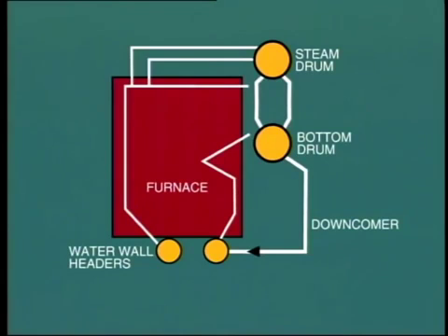Means must be provided for draining the boiler of water in the case that certain maintenance work needs to be performed. For this purpose, large drain valves are fitted at low-level points such as the bottom drum, downcomers' low point, bottom water wall headers.